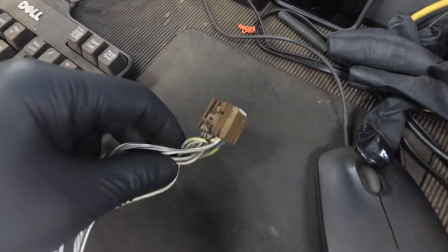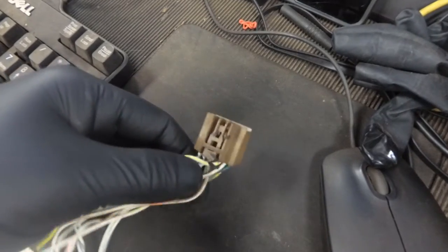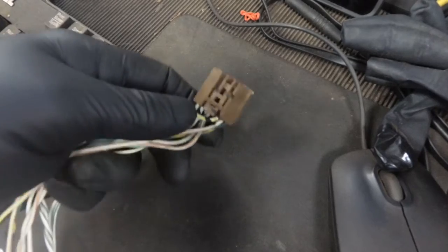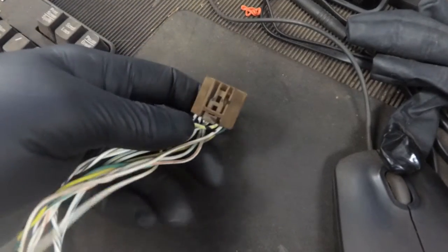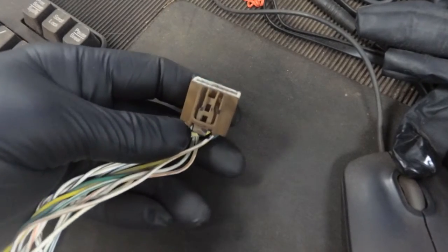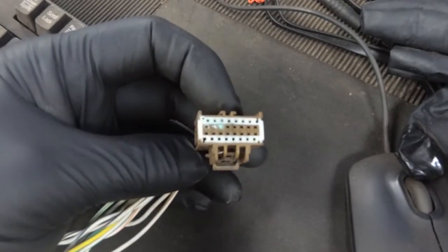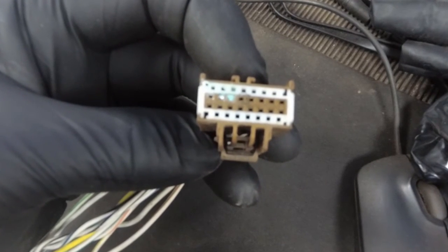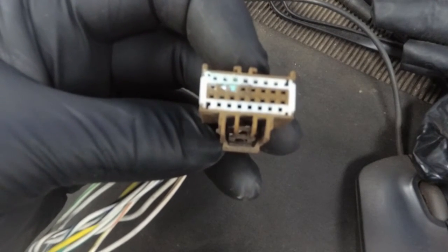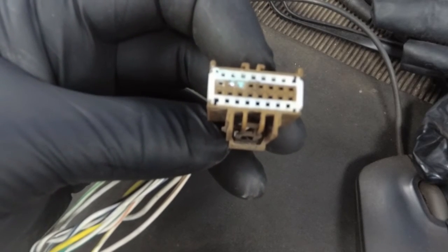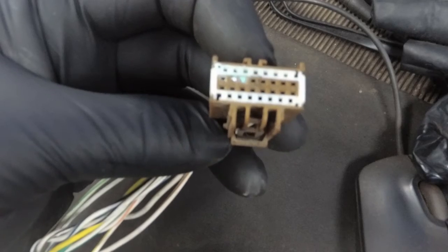So I needed one of these terminals, so I went to the local wrecking yard here, and I got a previously enjoyed connector from one of the TIPMs out of a 2008, which is the same. And this is the exact same connector here. Now the interesting thing is I took this connector out of a running truck, and you'll notice the third pin down on the top row. That's the same pin 11 that was corroded off, and it's also corroded off on this used connector.